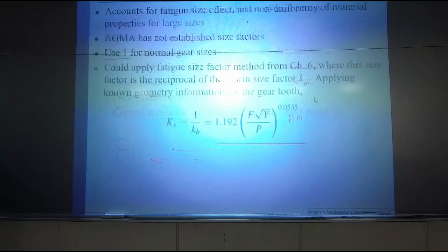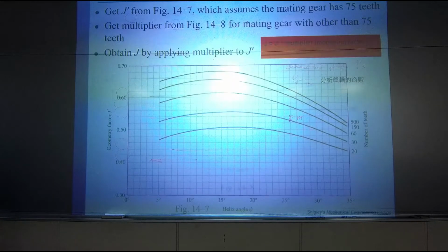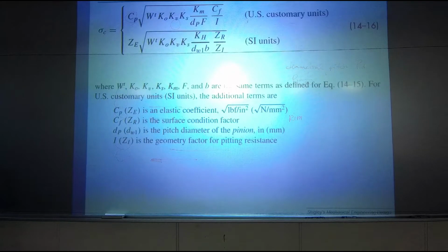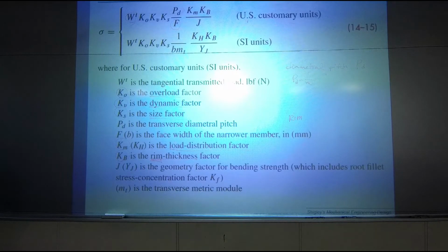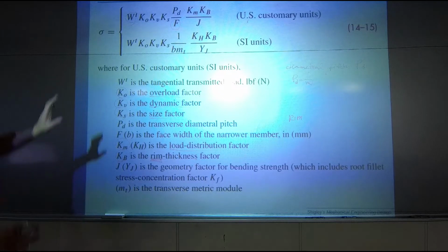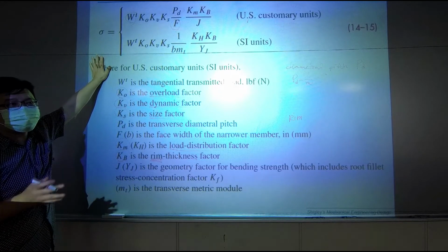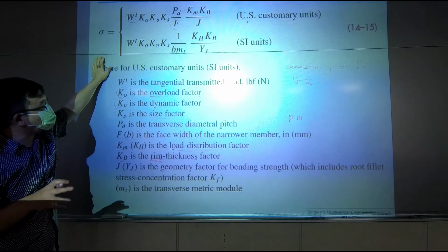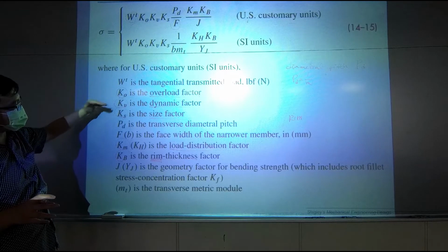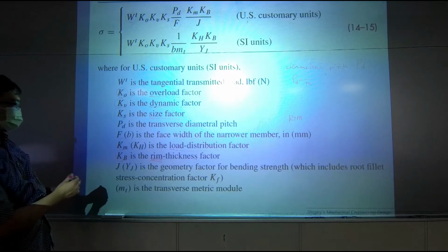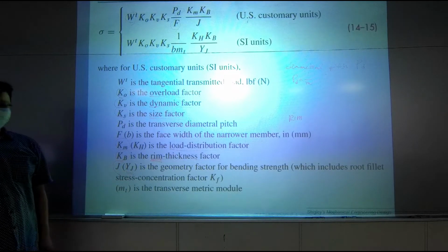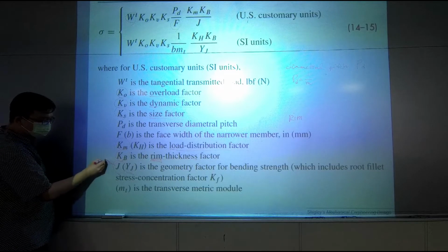So let's get back to the general equation. Okay, so over here, like I said, the stress not only depends on the equation that came from Lewis, but also has a lot of correction factors. And there is a J factor. J is related to Y. Y is the Lewis factor. Okay? So J is related to the Lewis factor.